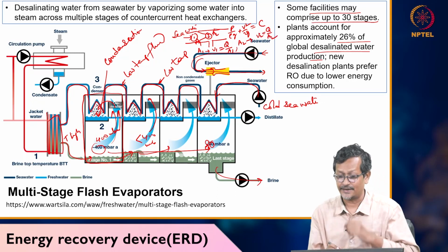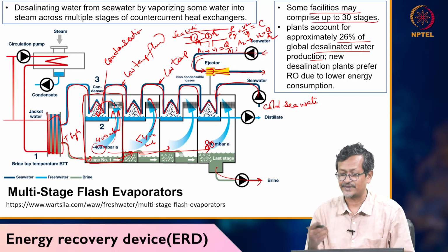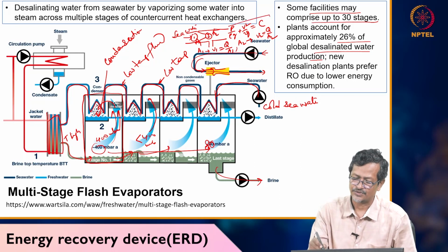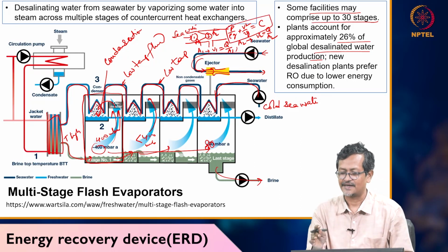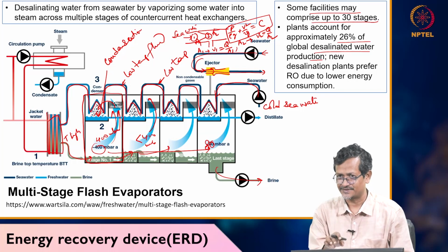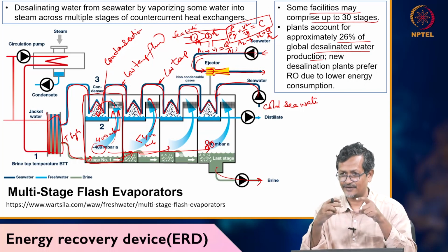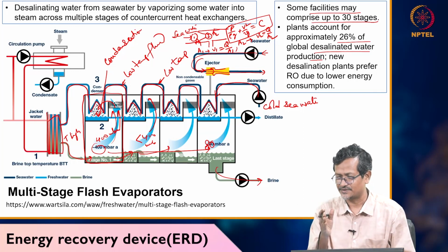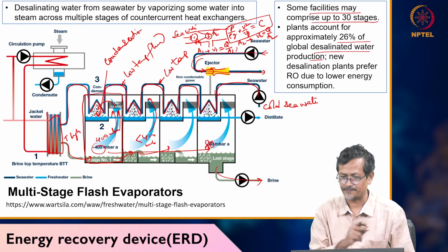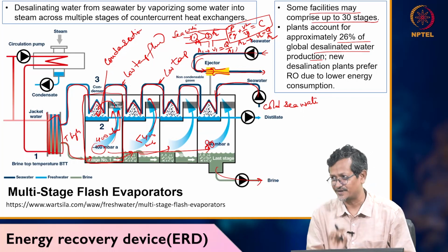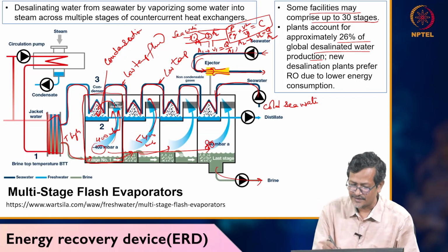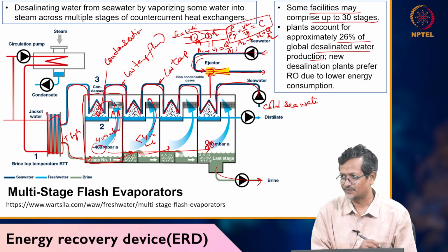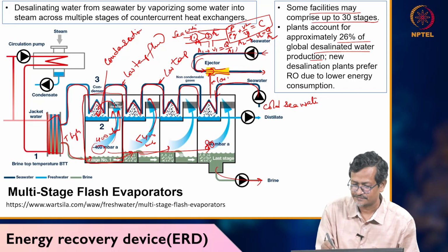You see this area reduced. So, area reduced means velocity 2 is increased. When velocity 2 increases, you go again to Bernoulli's equation: velocity increases, so pressure must be reduced. This is the energy equation, so you are not destroying or creating energy. So, when velocity increases, pressure must reduce. At point 2 your pressure got down, this pressure becomes lower, okay. So, this is low pressure.